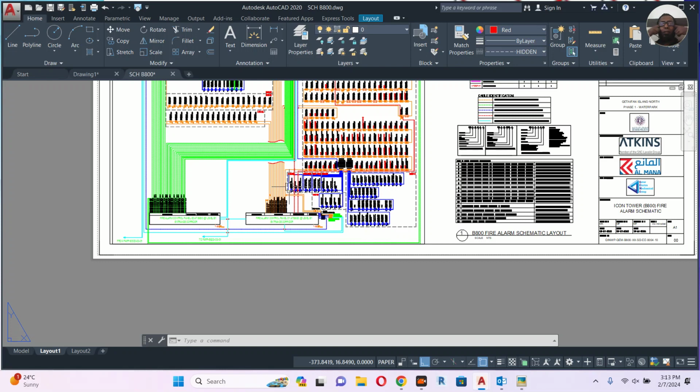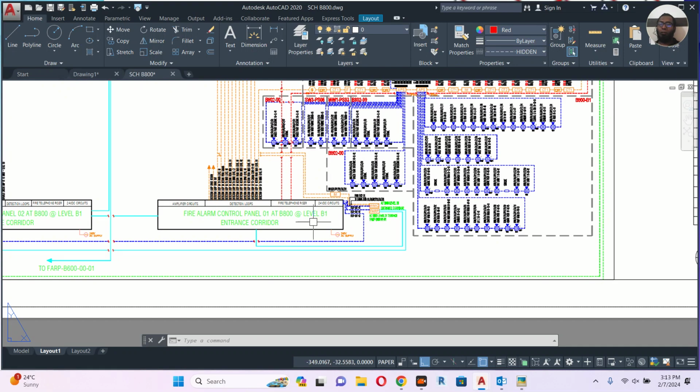Like let's say we have an AHU supplying cool air to the room or anything, supplying air. So in case of fire, it should be stopped. Then exhaust should start, and the pressurization fan will start. Fresh air should start. Something like that. It will be controlled by the smoke override panel. It will connect directly to the fire alarm control panel.